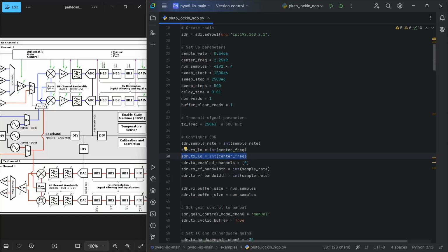But the issue here is that, as you can see here, for noise reduction in our SDR, we have a 200 kilohertz to 56 megahertz filter after our DAC, right? Which basically wants to reduce the tones at the output of our DAC, right? So if we just make a constant voltage at the output of our DAC, the chances are that our filter may reject it, right? So what we do here, for lower attenuation, is we create a sine tone also at the output of the DAC,